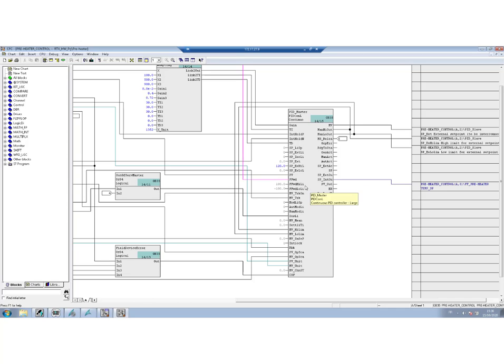The idea is that what is coming from the feed forward and what is coming from the PID control algorithm is added inside the PID controller, and this sum is limited, saturated between MV min and MV max. And in this case, it's not MV min or MV max that is used, right? But you clearly also have these parameters that allow you to limit MV between two values.